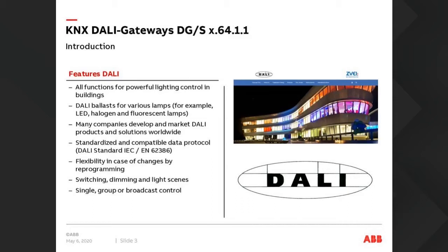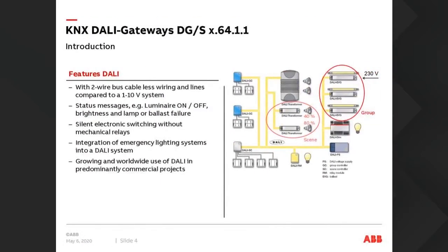Generally, we will control the lamps as a single ballast, as a group, or we can do a broadcast. We might decide to broadcast to a full DALI channel, and do whatever. We might have an all on or all off. Here's the features of a DALI system.